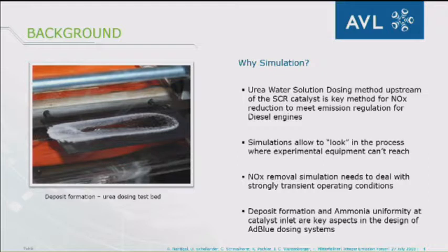The NOx removal process is part of strongly transient operating conditions, and deposit formation and ammonia uniformity are the key points for reaching high performance of the urea dosing process.